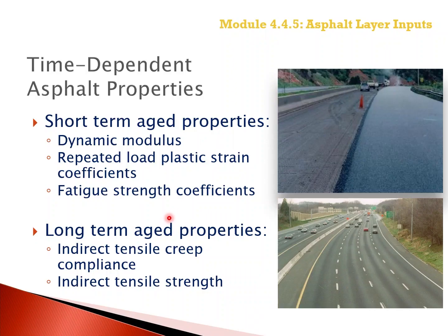The time-dependent properties entered in the PMED software are grouped into two categories: short-term and long-term aged properties. The short-term aged properties for measuring the asphalt properties include dynamic modulus, repeated load plastic strain coefficients, and the fatigue strength coefficients.